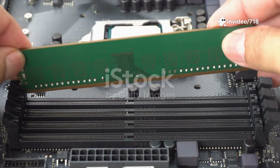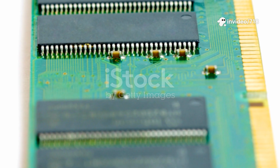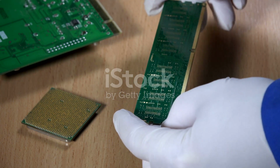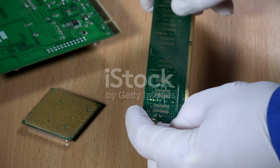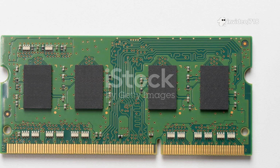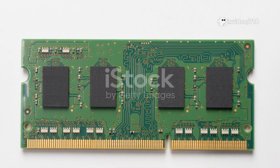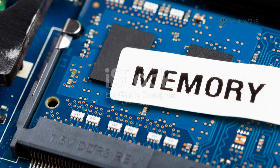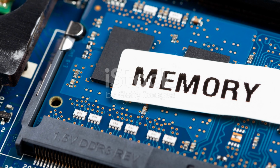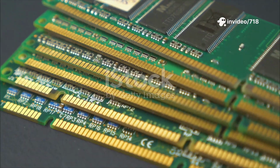Alright, so we've established that DRAM is the workhorse main memory in our computers. But it's not the only type of RAM out there. It has a close relative, a sibling if you will, called SRAM, which stands for Static Random Access Memory. The key difference lies in that first word, static. Unlike our dynamic DRAM, which needs constant refreshing to remember things, SRAM does not. It holds on to its data as long as it has power, without any need for a refresh cycle. This is because it uses a completely different and more complex internal structure.